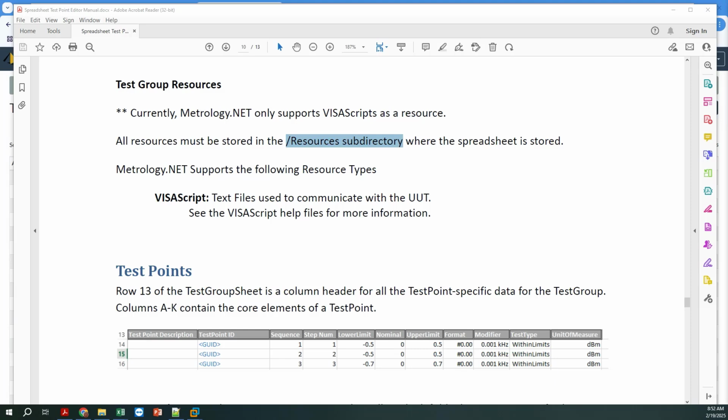Is there a way to make a resource communicate to the standard? No. Like, say, for instance, to turn the low I option on an 8508. So there is a way to do that. And when you sit back and look at the metrology behind that, the low I option is a current limit; the device doesn't want you to put more than a certain amount of current in it. When you go back and look at the updated taxonomy for resistance, you'll see that we now have a current setting. And by adjusting that current setting, the driver will handle the low I setting.